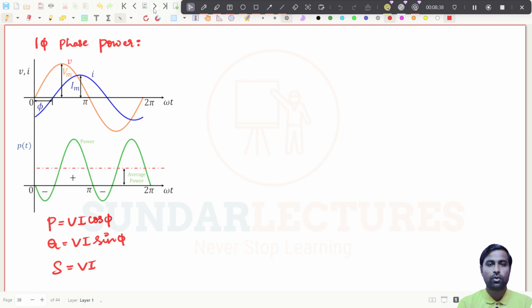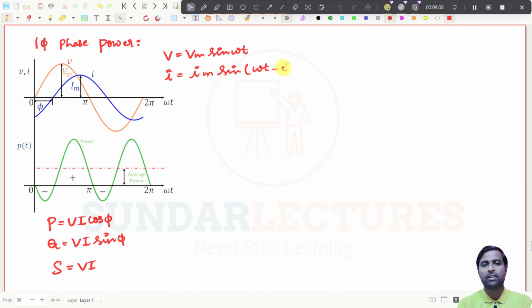So what we have done: this is the voltage curve, and this is the current curve. See here, current is lagging by an angle phi, right? So V will be equal to Vm sin omega t, and I will be equal to Im sin of omega t minus phi.